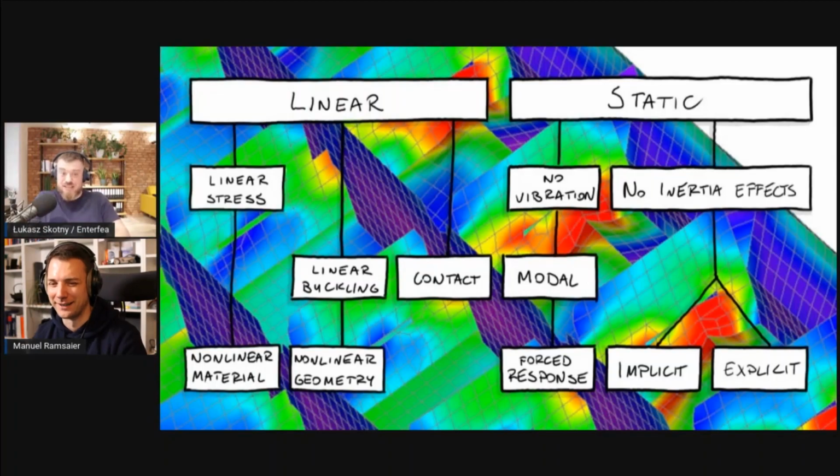In some circumstances it could be hard, a freaking nightmare. Right. And also make sure that the penetration is not too large with contacts, because you could have it converged, but then it's penetrating like crazy, like multiple millimeters and stuff like that. Then it's also not really a thing.